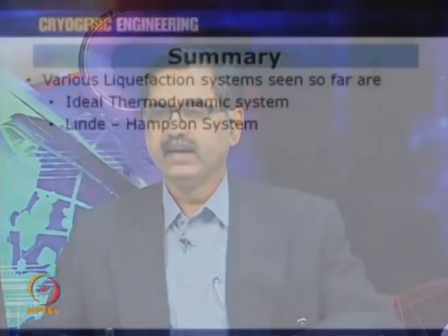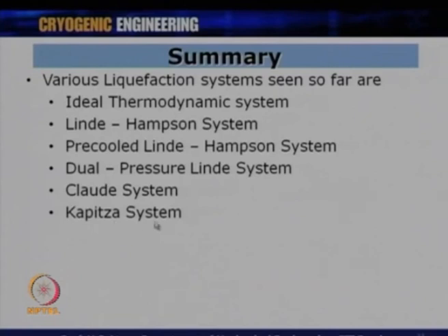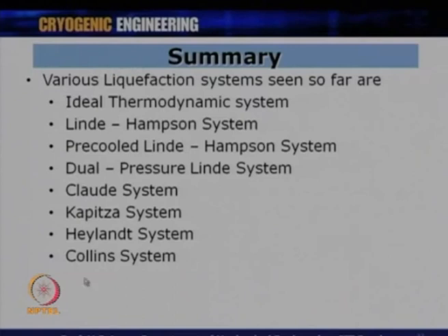Now, what we have studied are various liquefaction cycles: the ideal thermodynamic cycle, Linde-Hampson cycle, pre-cooled Linde-Hampson cycle, dual pressure Linde system, then Claude system, Kapitza system, Heylandt system and Collins system. We have studied all these systems with their TS diagrams and schematics, and we have solved various problems or taken various tutorials to understand how each cycle evolved, how each cycle became better and better, or how one reaches lower and lower temperatures using various expansion devices.